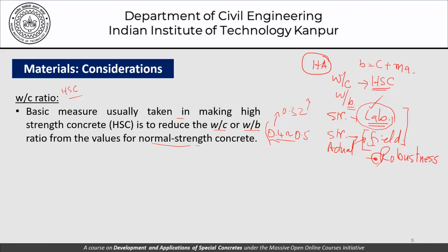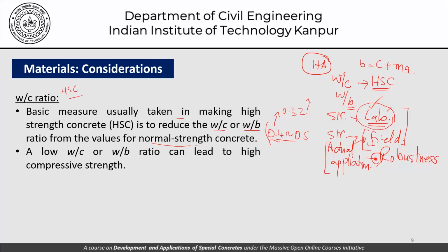as far as actual applications is concerned. There are differences when it comes to field applications or actual project applications of high strength concrete because of the nature of production, the curing and so on, and that prevents us from achieving the kind of results that we achieve in the lab in the field conditions.